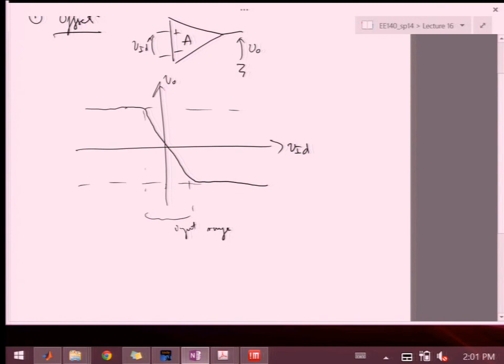and after a certain input range, the current will swing all the way to one branch or the other, and we would have no dependence between input and output anymore. So that's called my diff pair got saturated, right? It got swung one way or the other. So all the amplification is really happening in this range.